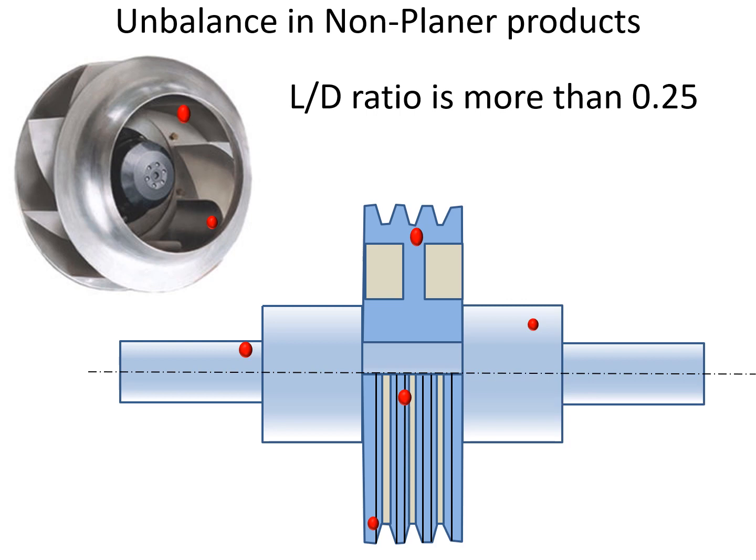In these cases, we find that there may be some unbalanced masses in different planes rather than in one plane. For example, you see the red dots that I have shown. These are some unbalanced masses which cannot be seen with naked eyes. They are present within the system because of manufacturing inaccuracies. So we will learn how to take care of such conditions, or how to balance such cases when the unbalanced masses are in different planes. This kind of balancing is known as dynamic balancing.